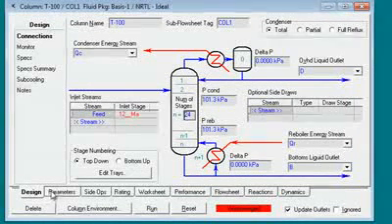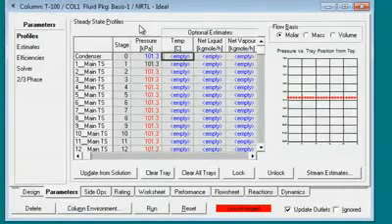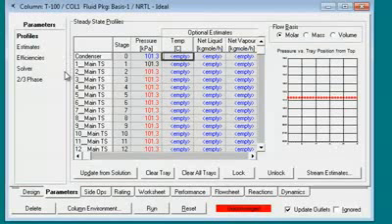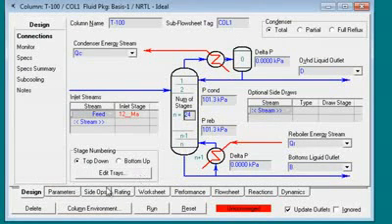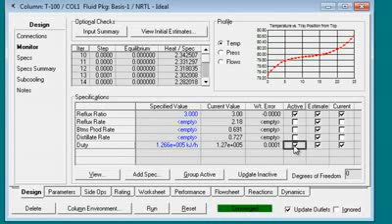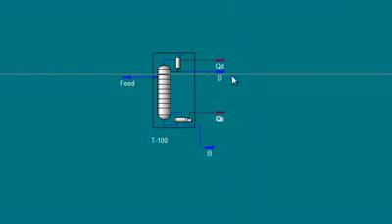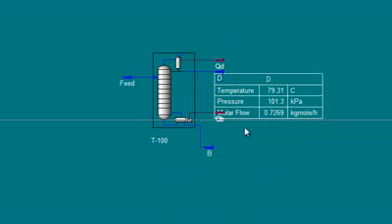We should go to the parameter here, and here the temperature we should remove it, because we don't know the temperature in the distilled or in the bottom. We put the temperature is 25. So now we go back to the design, or then monitor, and here you can tick on specification here, and you can see it's covered. And here is also it's running. You can see run, it's covered, and here everything is done. Here you can show table of the result.